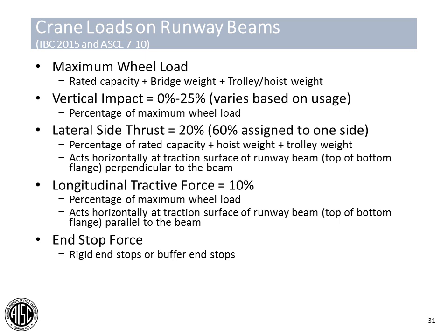That's why the wheelbase, or the wheel spacing that we saw in an earlier slide, is critical, because you do have to apply multiple wheel loads at one time, which can substantially impact your moment diagram on both your strong axis and weak axis design.